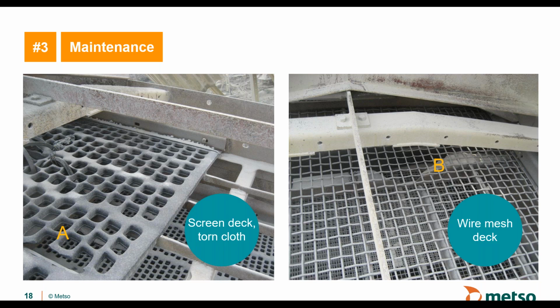In this case, it looks like the protective rubber that should have been on the stringers is not there. And so you get a gap between the cloth and the stringers. And during operation, the cloth will then bounce on the stringer, and the cloth will eat up the stringer, and the stringer will be destroyed eventually. And when the stringer is not the correct dimension, there are difficulties. You cannot really tension the cloth again, and this will happen again.